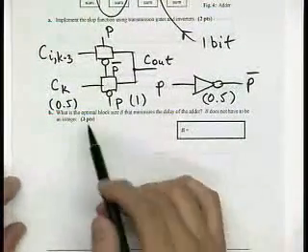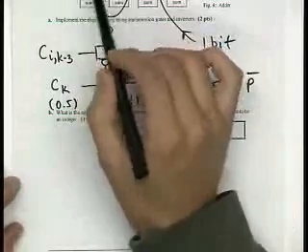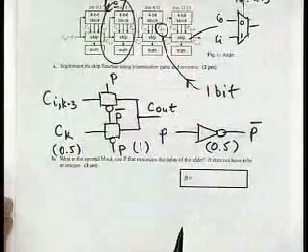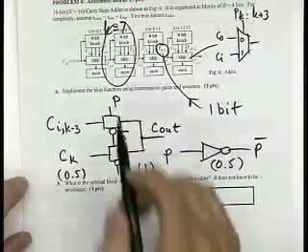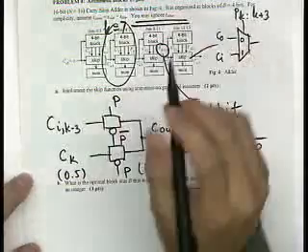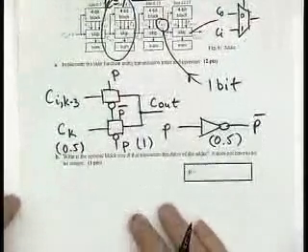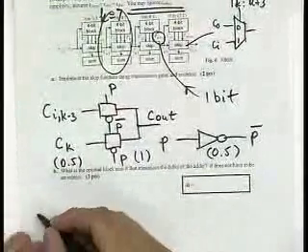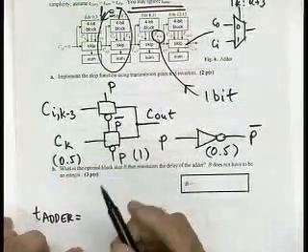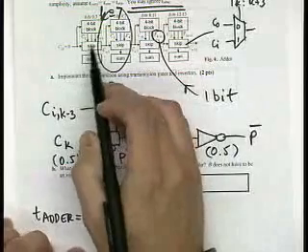So the next question is, what is the optimal block size B? In this case, B was equal to 4-bit blocks. That will minimize the delay of the adder, assuming that all of these delays are equal, and you can ignore the setup. This was important to observe. So now first you have that your T adder is equal to the following. So you have B blocks over here.